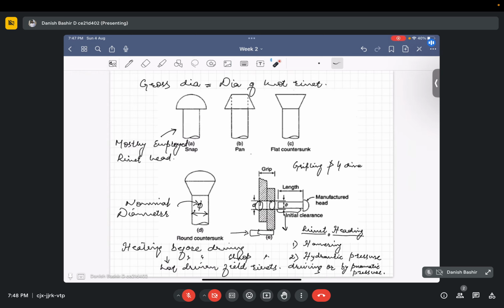So using a hammer we have to hit it from one side. If it is loose, it will make a small metallic sound. That metallic sound we have to detect, and we have to replace those rivets, because it's very important in our steel design, as these connections keep our structure together.